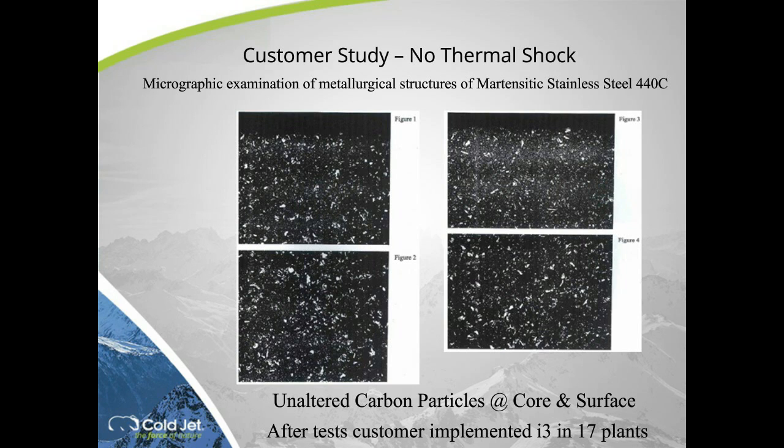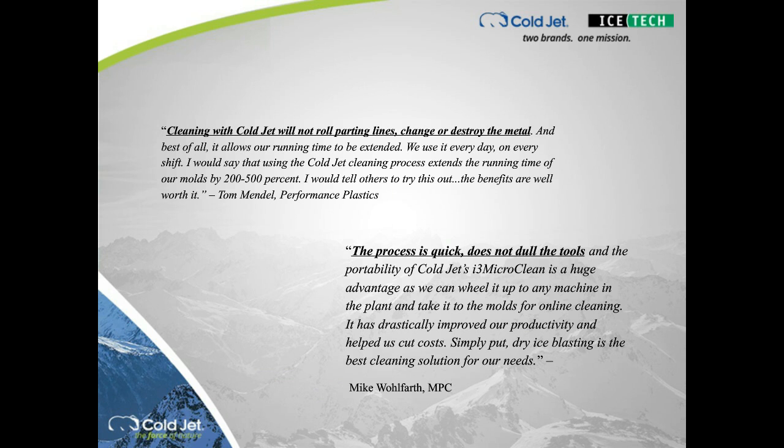We had a customer do their own independent study on wear and on thermal shock, standing on stainless steel, very common in medical device molding, and they did not alter the carbon particles at the core or the surface. They had no damage cleaning with dry ice. And people tell us that. It doesn't dull the tools, it doesn't destroy the metal, it doesn't change the metal, it doesn't roll the parting lines, it doesn't roll the shutoffs. Beautiful way to clean quickly without damage to the tool, without having residual waste.